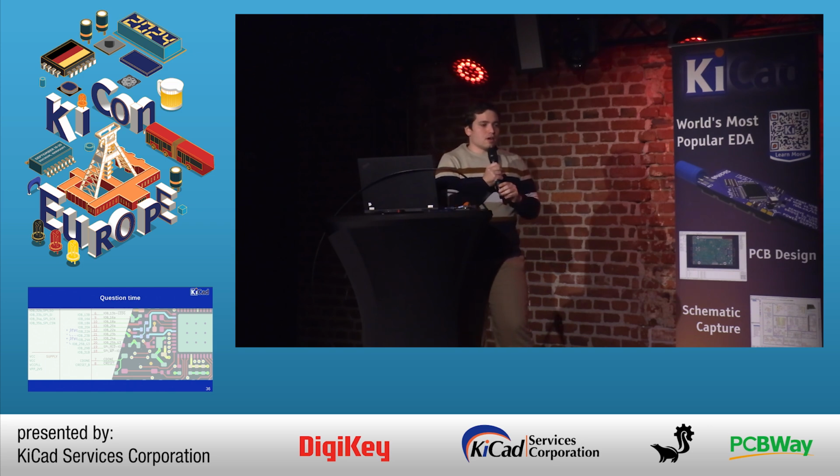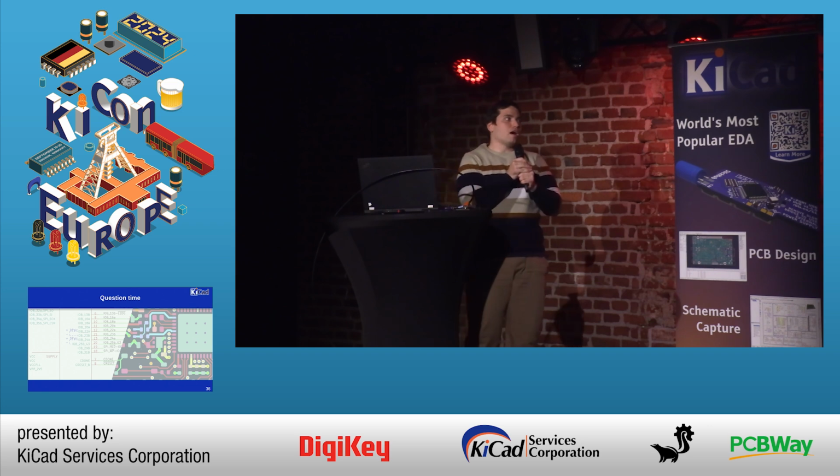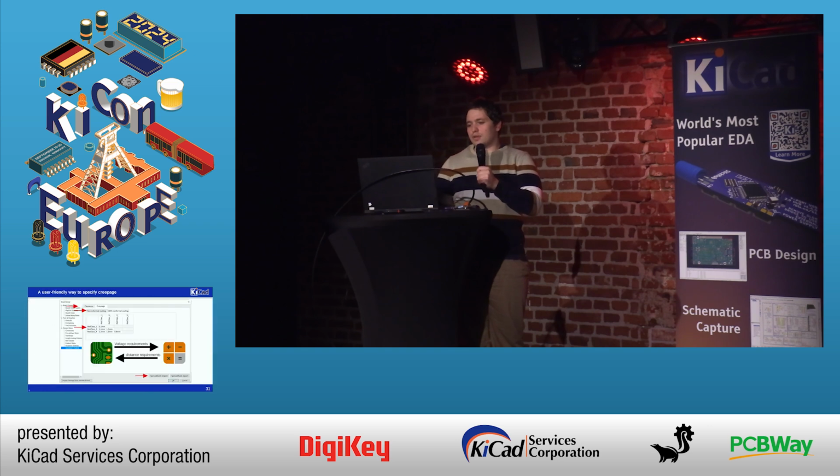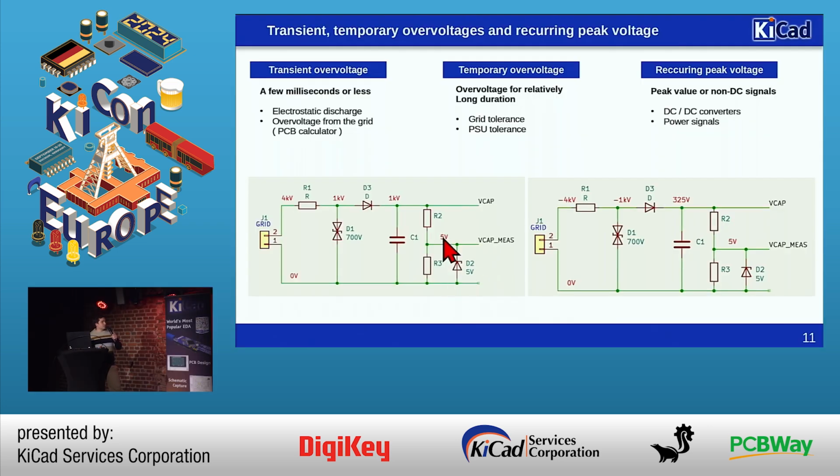Two things should only be in the same net class if they have less than 10 volts difference. For example, 0 volt and 5 volt can be in the same net class for isolation purposes because there's no creepage or really clearance requirement apart from manufacturing between 0 and 5.